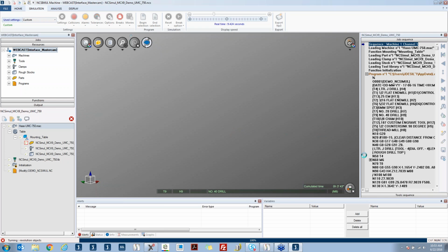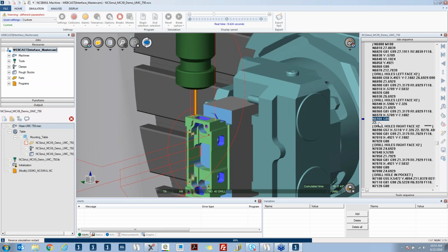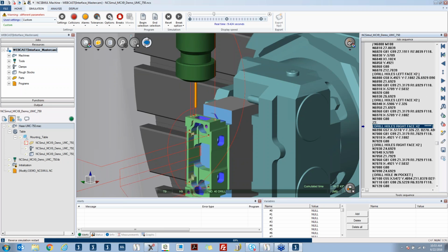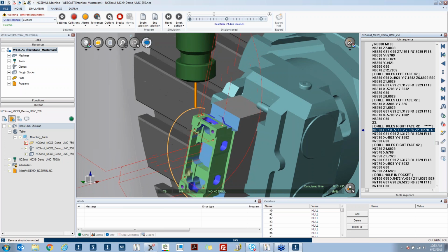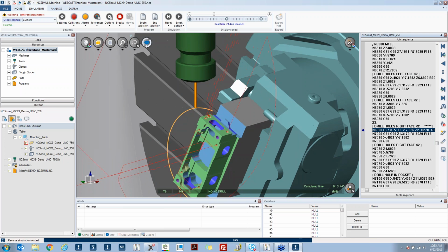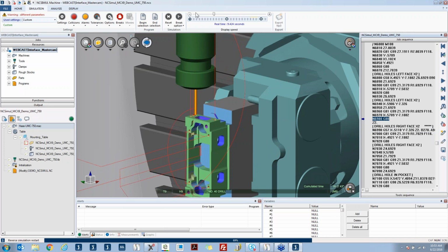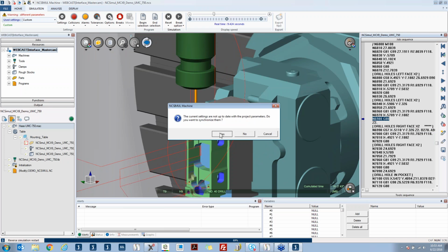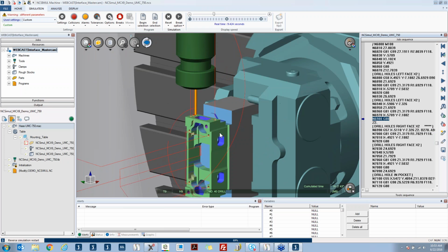Finally, we can see now that I no longer have the issue, because now it goes to 2 inches in the Z-axis, and when I rotate around, I can clear the piece without having any collisions. Again, I'm going to pick up right from where I left off and say yes and yes to this.